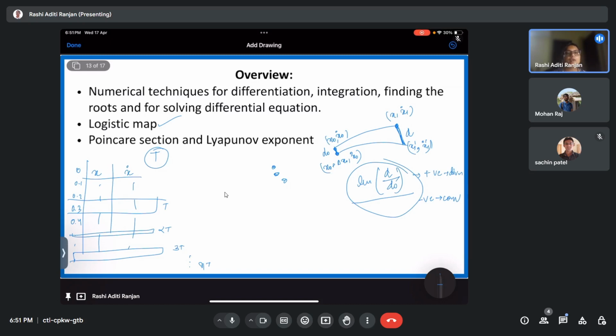But windowing is something that I have dealt with, because I remember that we used to superimpose some kind of noise on our signal in order to find out the natural frequency. Because of the noise, the natural frequency was not correct. So we were windowing our function, and after windowing, we were able to get the exact natural frequency of the system. So I guess that would be helpful for your work. Yes, madam, I will try that.